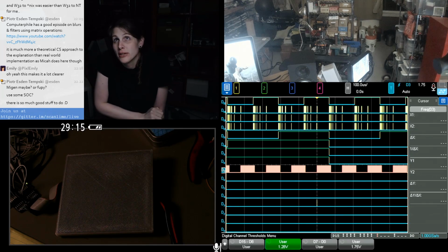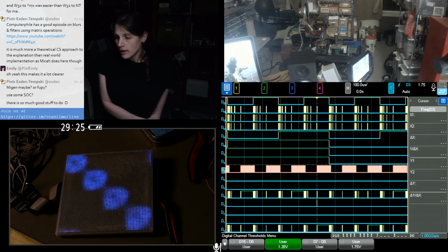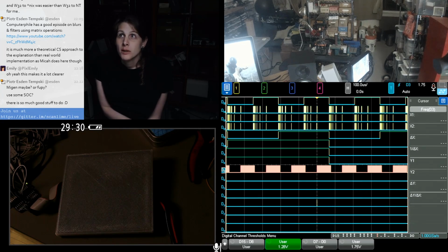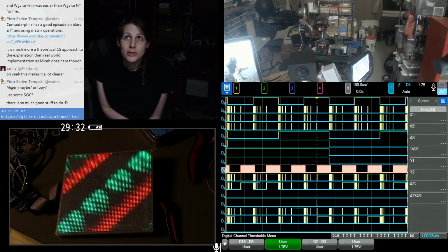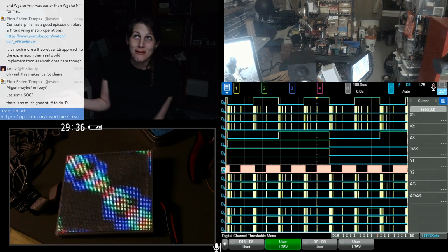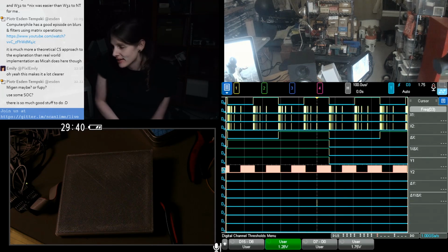A lot of people do it. You can find libraries for Raspberry Pi and Arduino that generate these waveforms in software, but they're usually not quite as stable as this and can't quite push the LED panel to its limits like this. So the FPGA is a great choice for generating the waveforms, and especially for the brightness control. This level of brightness control would be really hard to get without an FPGA, whereas this just makes it easy to push the panel to its limits.